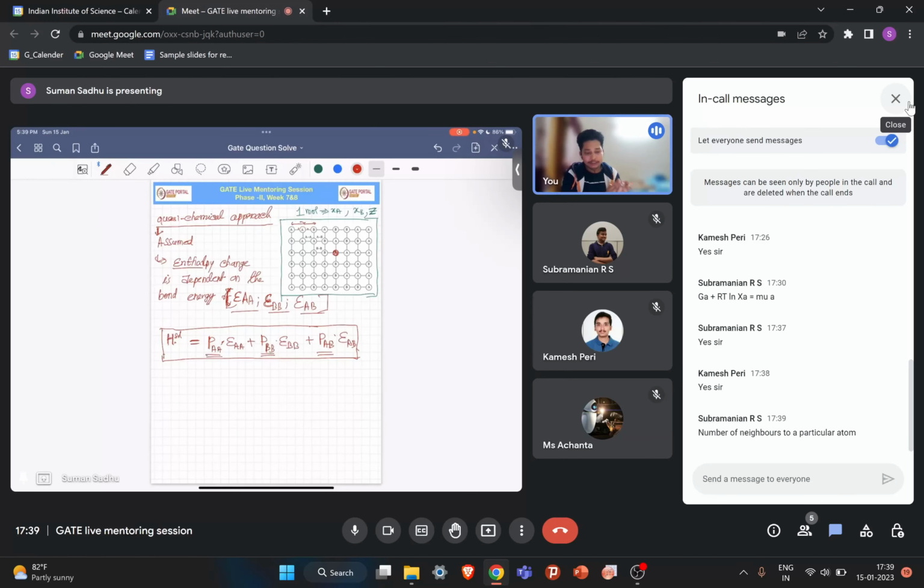It will have Z number of neighbors, if the coordination number of this system is Z. So what will be the probability of finding an A and A bond? It has Z neighbors, but not all of them will be A atoms, because you have B atoms also in your system. XB mole of B atoms is there, and XA mole of A atoms is there.